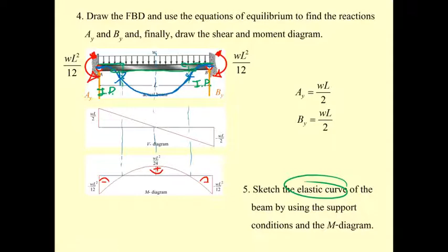So now you can sketch the elastic curve, and you also put the reinforcement pattern into it. Okay, you go back and try to work on this. I believe you guys can do it, even though it is 1 degree of indeterminacy or 2 degrees of indeterminacy, and I don't think we can do manual calculation for 3 degrees of indeterminacy. That is too tough.